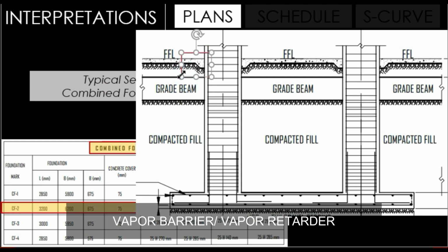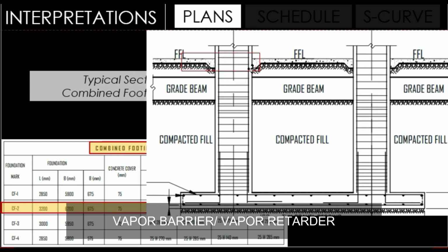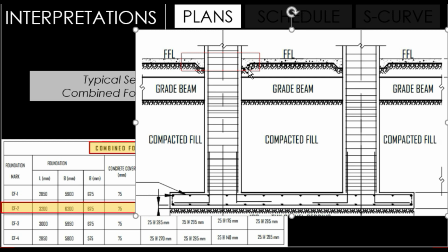If you have a concrete floor in continuous contact with a source of moisture, you will have problems. This is why vapor barriers or vapor retarders are used under concrete. It is essential. Vapor barriers are a way to keep moisture from getting into the concrete.